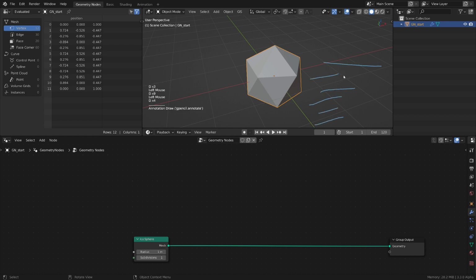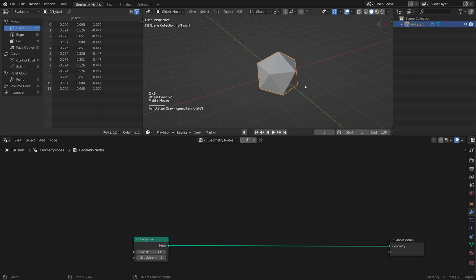You don't care about the location, and then you can take the position of the points of this mesh in a random fashion using, for example, a math done on the index. So you get the position of some random points of the mesh by doing a random stuff with the index, and you transfer those positions to the ends of the segments of the lines. So those segments will be basically ported here on your mesh. That's another approach that can have benefits depending on what you do.